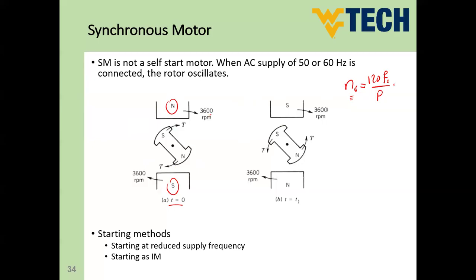As we mentioned before, guys, the synchronous speed has some definite values. It's a good chance also to discuss this point, because as you can see here, the number of poles cannot be a fraction. It has to be a whole number, a multiple of 2, an even number. So 2 poles, 4 poles, 6 poles, 8 poles, and so on.